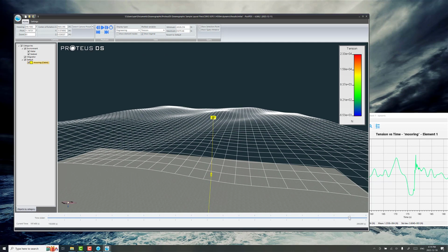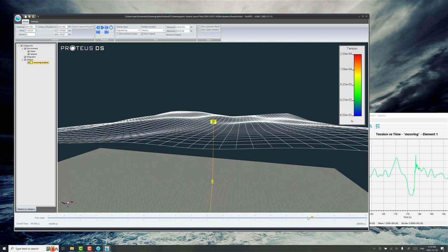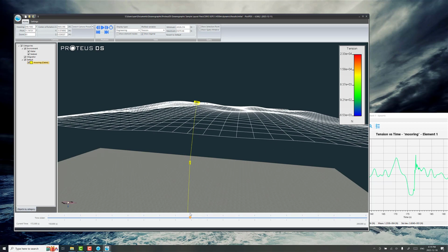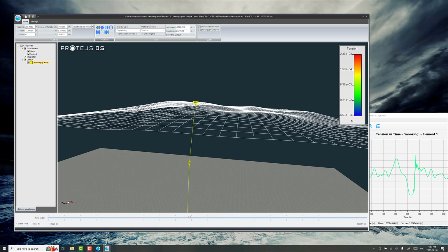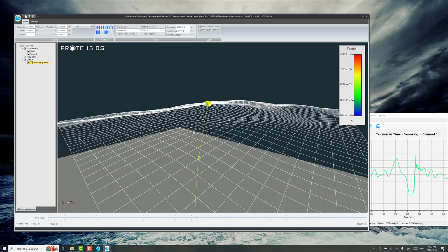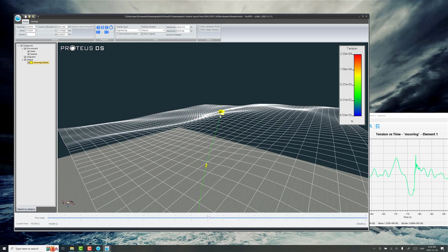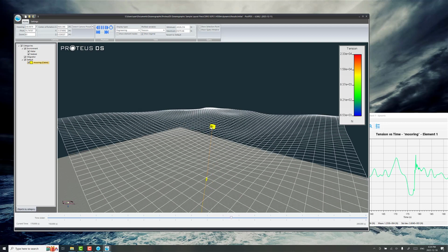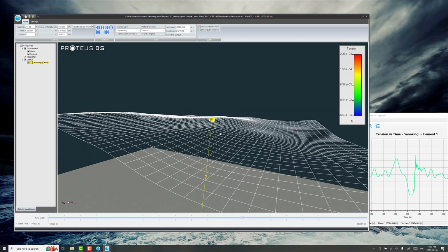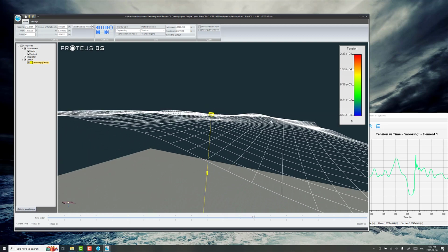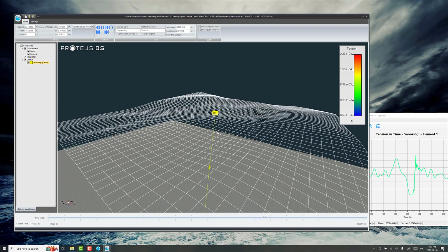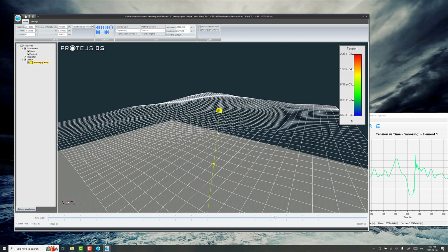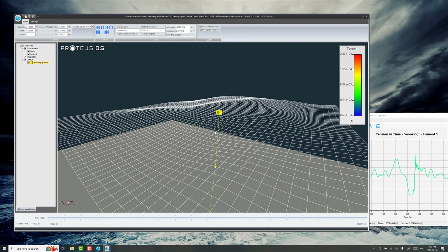You can also get this information from the report tool, and then it's kind of interesting to go back and look at it. So it says there's a shock load around here. Let's just see what happens. So a big wave is going by. That's typically what happens. Yeah, the mooring is getting unloaded, so the tension's getting very low, and then it gets slammed when the whole system accelerates back up this kind of steep wave. So that's just typical dynamic loading in this kind of scenario when there's lots of accelerations and pretty steep waves.